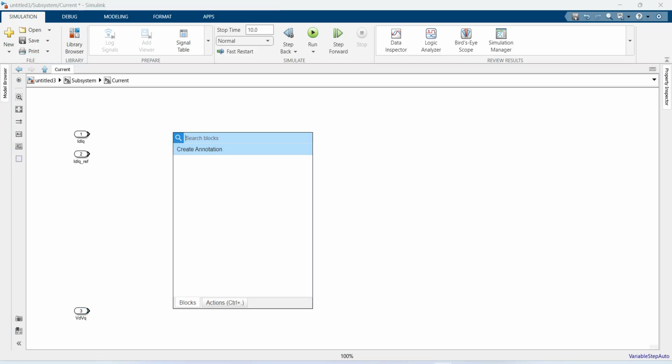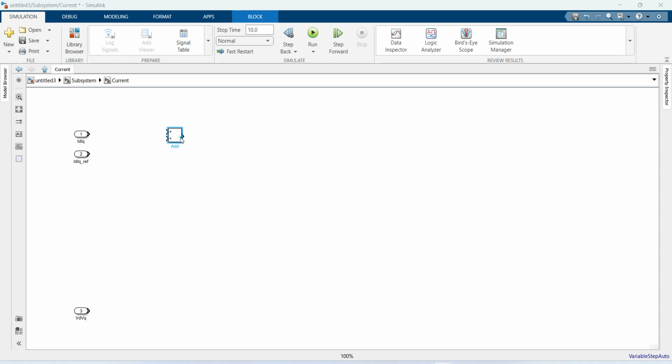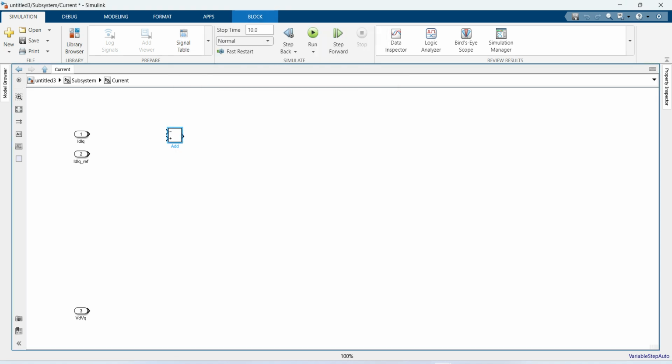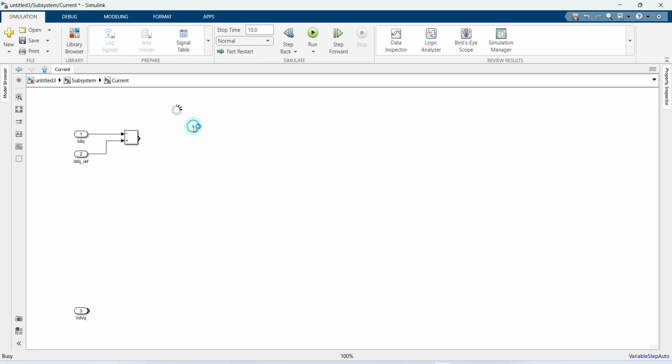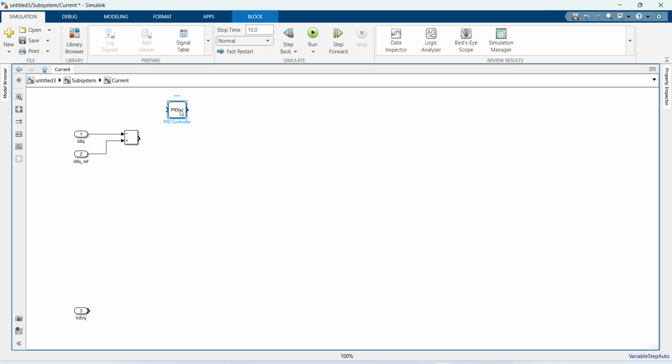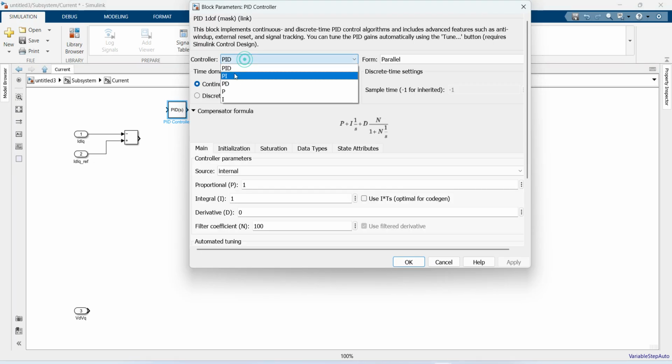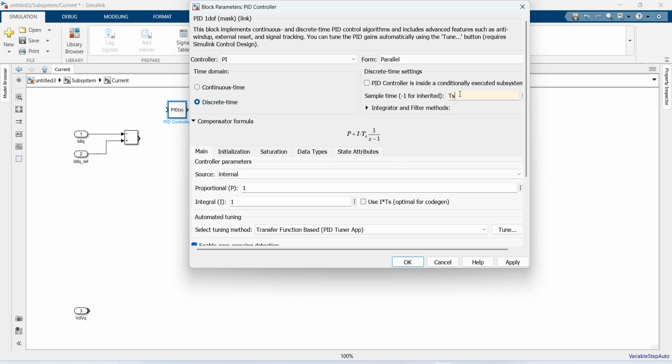Okay, so from this IDIQ we need to add a subtract block. So from this IDIQ reference, the main IDIQ will be subtracted, and then we need to feed this to a PID controller block, and it will be PI, and the sample time will be TS control. Okay, and it will be 0.15 and 6.6.